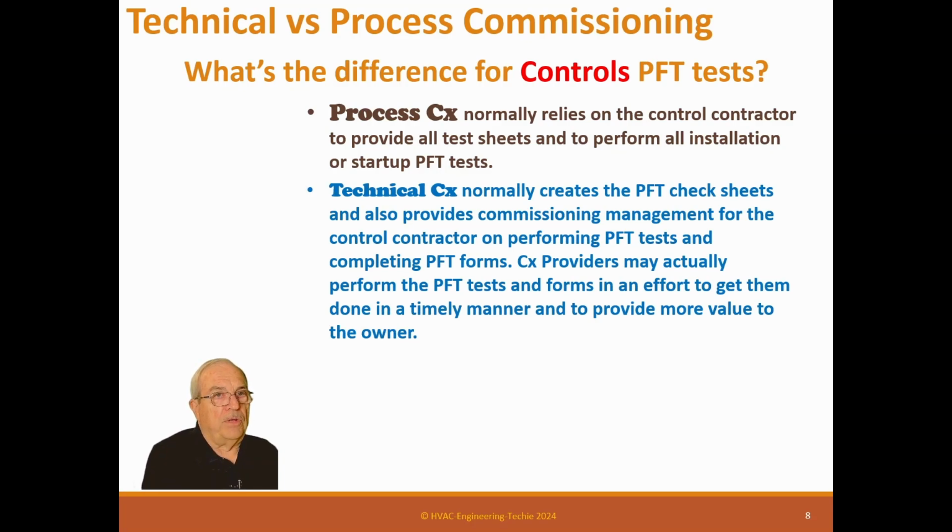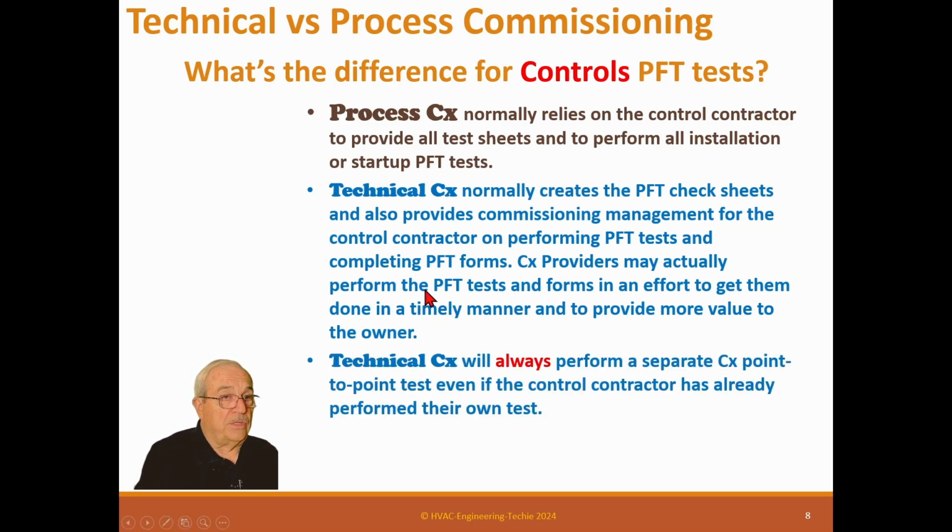Technical commissioning normally creates the PFT check sheets and also provides commissioning management for the control contractor on performing the PFT tests and completing PFT forms. CX providers may actually perform the PFT tests and forms in an effort to get them done in a timely manner. This is a little harder for control. We normally have them do it and observe them, but remember, we're doing another point-to-point test anyway. So this becomes less important to us because we're doing that. Technical CX will always perform a separate point-to-point test, even if the control contractor has already performed their own test.